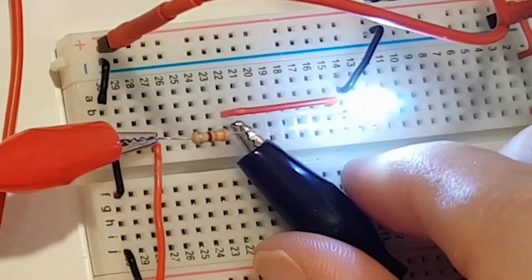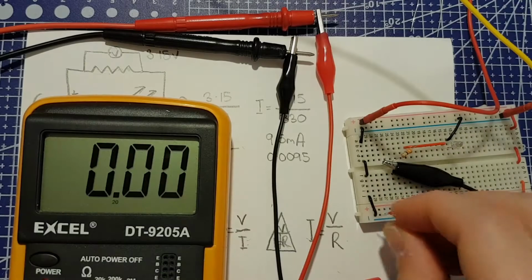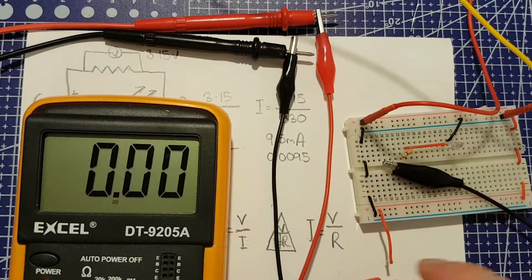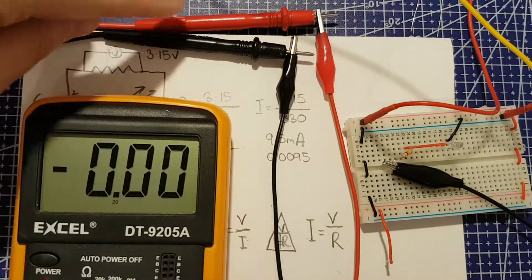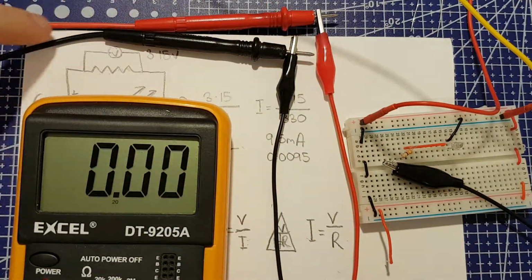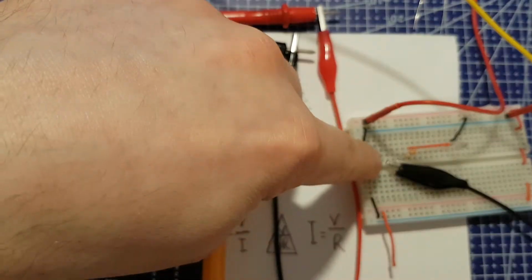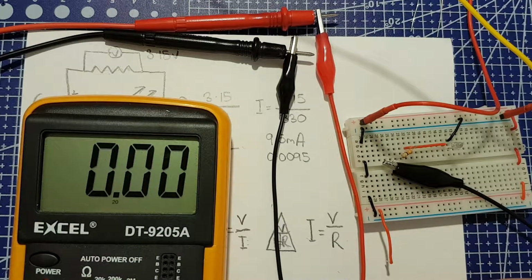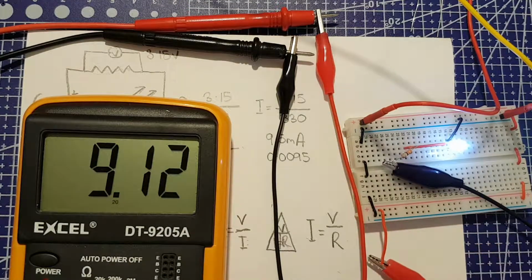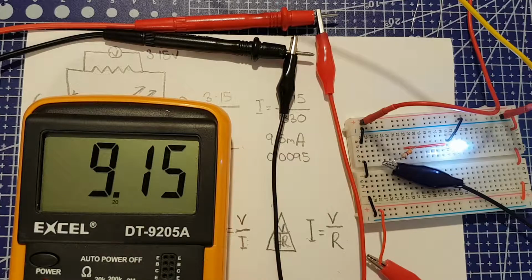So next step, we have positive coming out into the meter, through the test equipment, out of the meter, back into the other end where the positive would have attached to. LED's lit, circuit is made, and we are getting 9.13 milliamps. Now we've concluded that it's all working the way it should do.